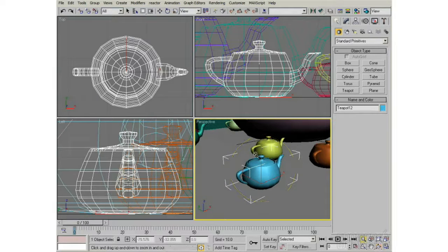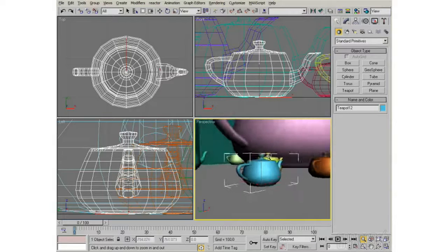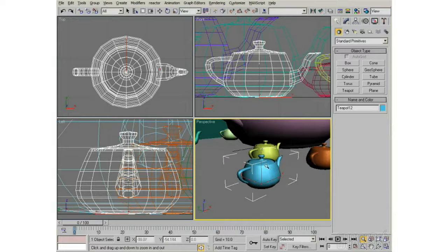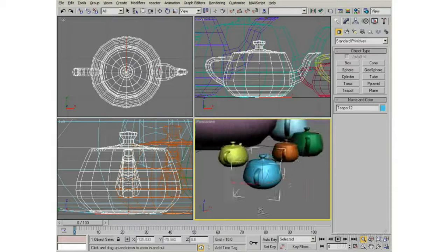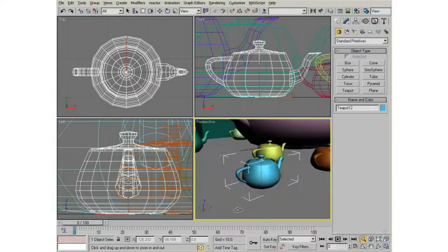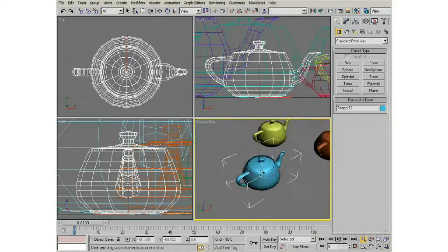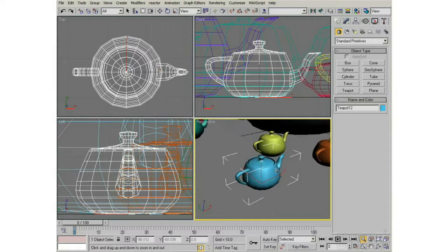And actually, you can do that with the middle mouse technique. If you hold down Alt and then also hold down Shift and you push the middle mouse button down and drag in one particular direction, you can see the cursor changes to a sort of constrained mode. And so you can constrain it to one view or another with the hotkeys as well. But you still might use this button because this button, as you see, has a flyout. So it's got 3 different modes of operation.